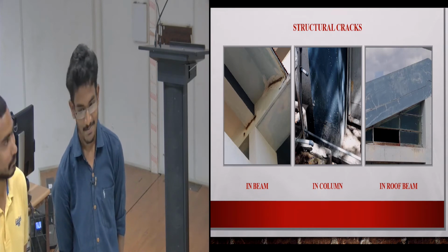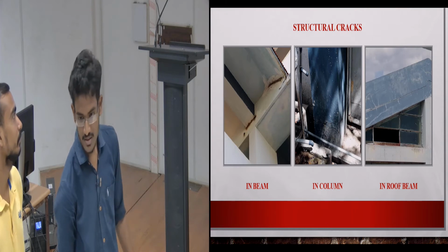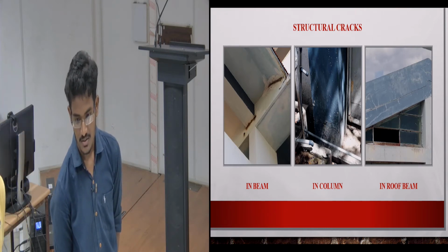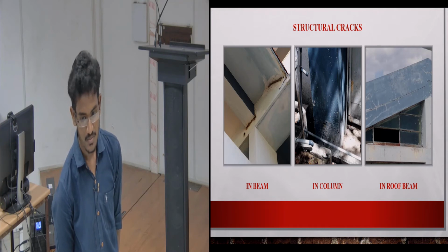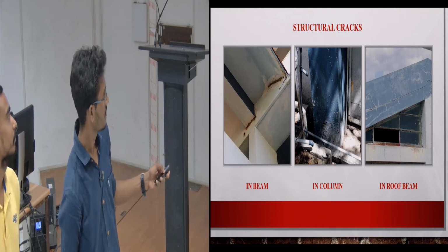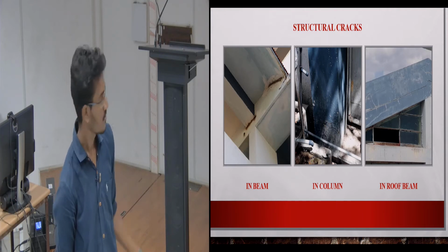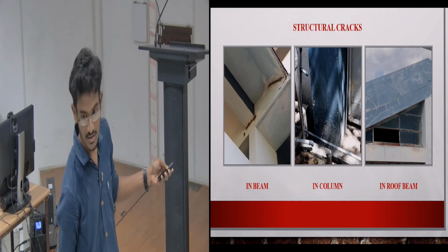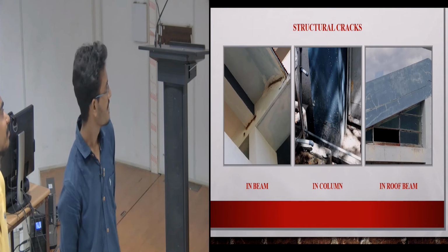The first picture you were talking about, because I asked you whether your building is safe or not. So what is below that? That's a sunshade, right? Yes. There's a passage below it. Yes, sir. Passage. Okay, that crack where the sunshade is connected, it doesn't look like a safe part of the building to me.